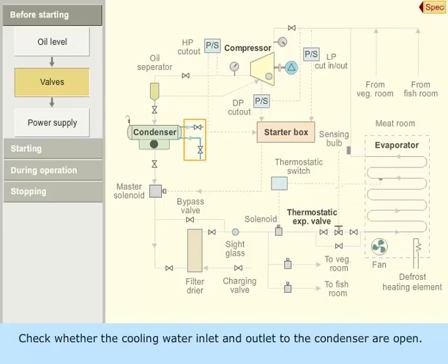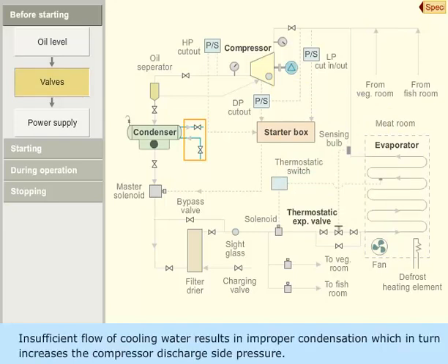Check whether the cooling water inlet and outlet to the condenser are open. Insufficient flow of cooling water results in improper condensation, which in turn increases the compressor discharge side pressure.